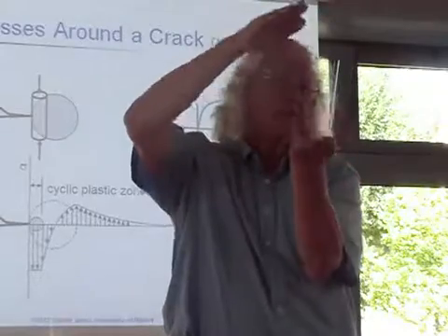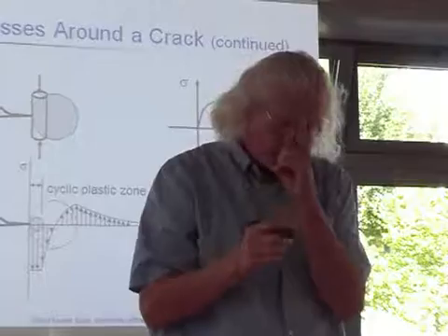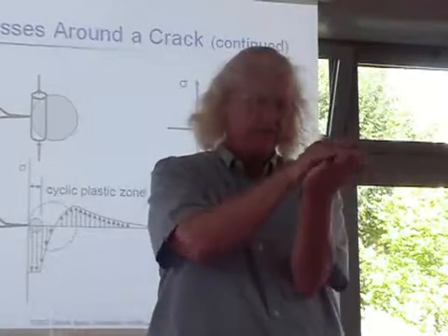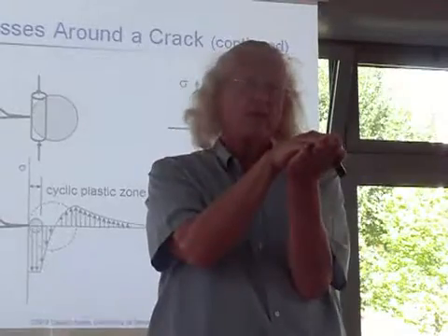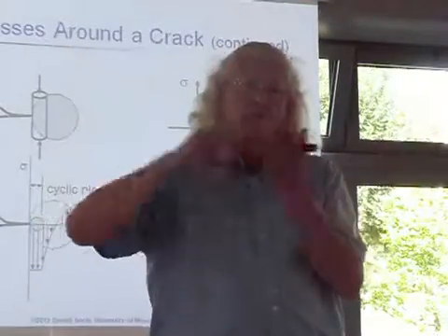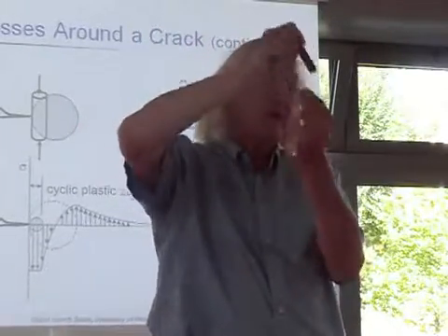So if your view about whether you can grow cracks in compression is the stresses around the crack, then no. But if your viewpoint is external loads, then it's easier, because it's very easy to have external compressive loads that produce compression at the crack tip.